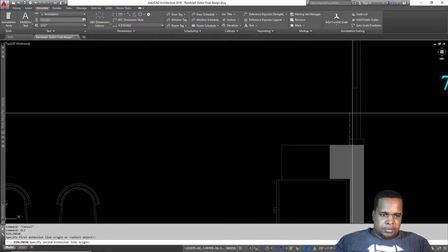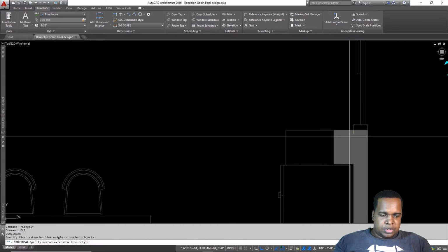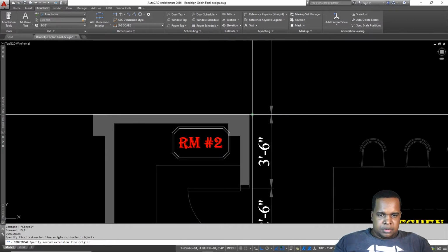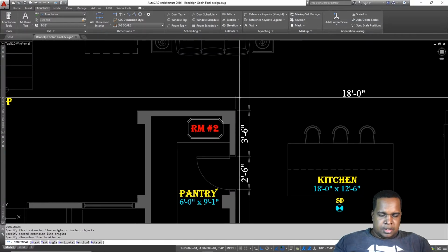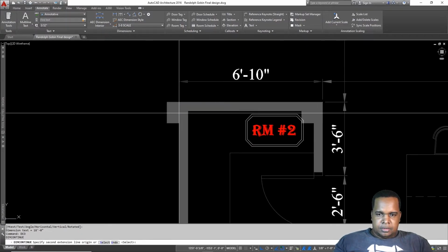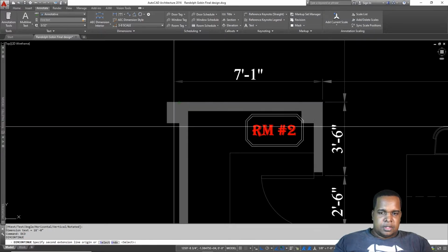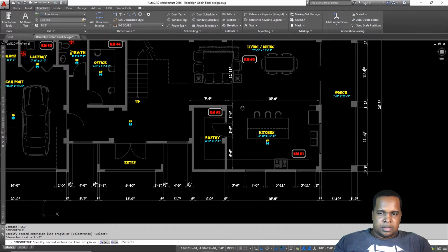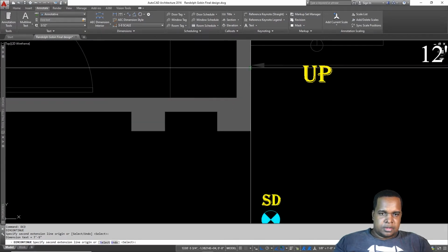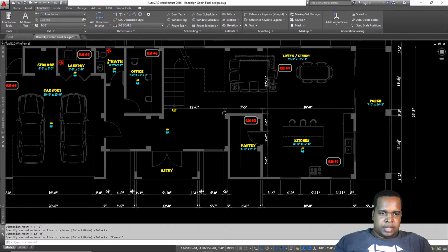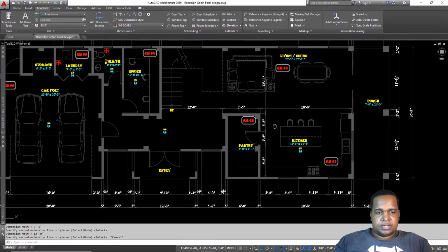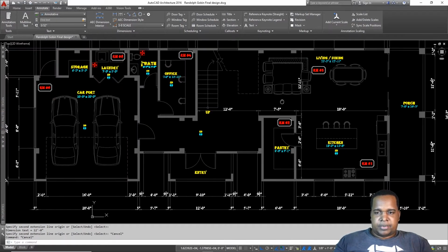Same thing, let's do so from the wall itself. So this is from the back door. We're not checking the column because we have a separate drawing for that. Right, so from the door to this point, that is 18. But in this instance, the wall stops here, so we have to go to the end of the column, right? And then we just go all the way to this wall. Right, so that way when they are on site and laying it out, it's pretty easy to find where the walls need to be and how far everything needs to be apart.